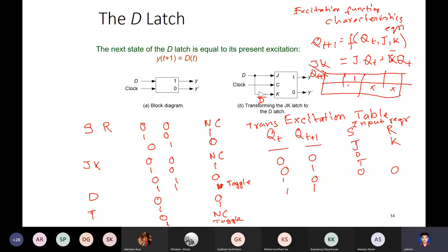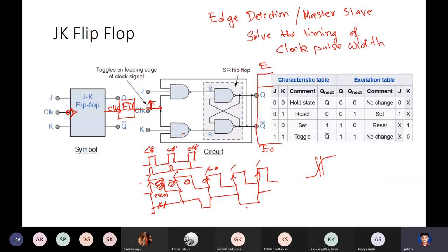So in any of these circuits, if you go through the entries of these Q, J, K values, the excitation function, you will be able to find out what Q is, just by the logic of the circuit. The key point is, whenever you are analyzing, suppose I give you some latch with some input, you basically do the same thing that you did in a truth table.